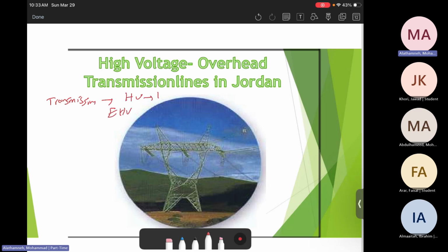High voltage is 132 kilovolts, and extra high voltage is 400 kilovolts. However, we have sub-transmission that's associated with medium voltage, and medium voltage can be either 33 kilovolts or 11 kilovolts. Here I'm talking about Jordan only.